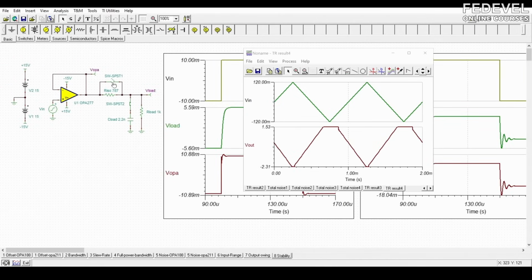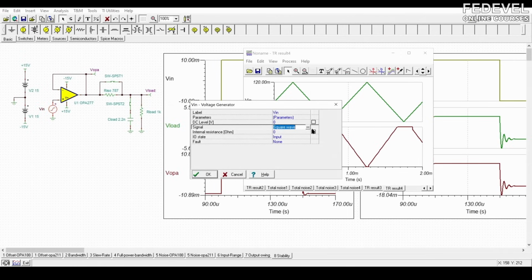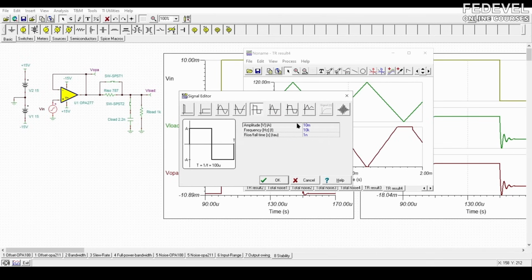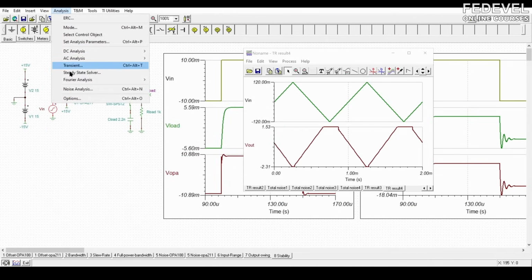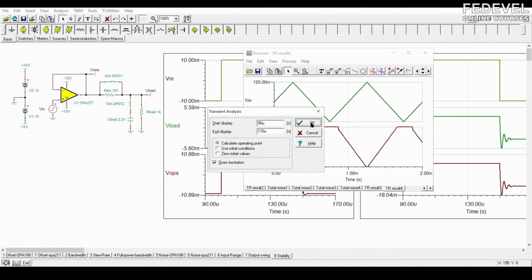First, we'll short out that resistor, and I'll show that the input signal is a small step, a 10 millivolt input square wave. And to test stability, you really want to use a small signal because we don't want this amplifier to go into slew rate operation. We want it to be a small signal. And we're going to use 10 kilohertz. And let's see what happens when we apply this transient signal.